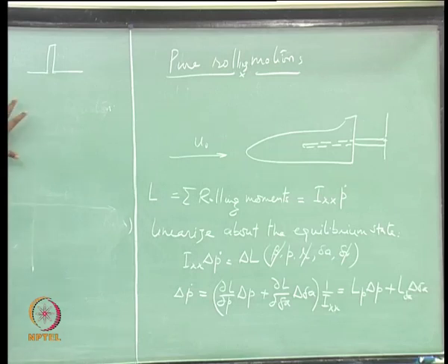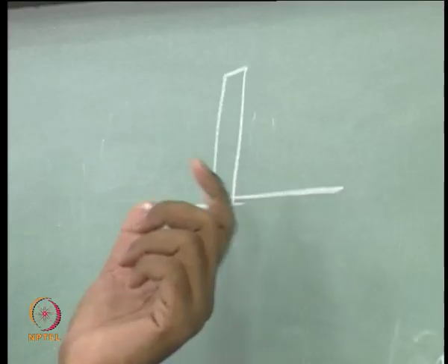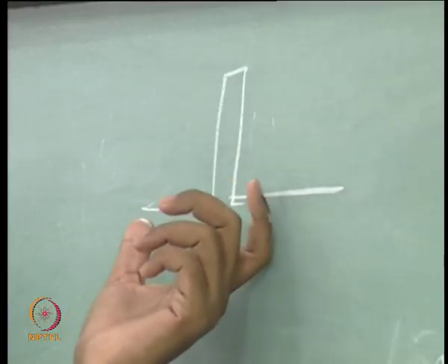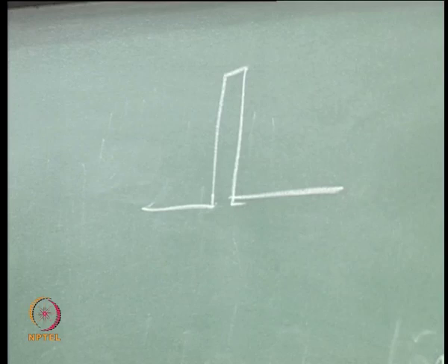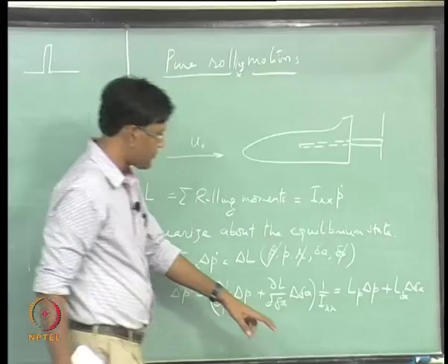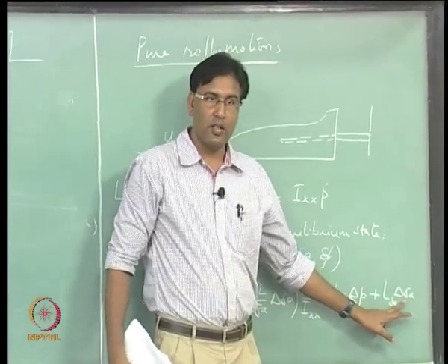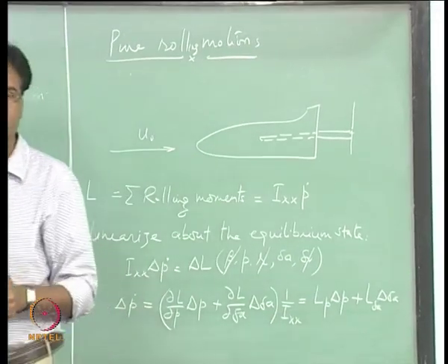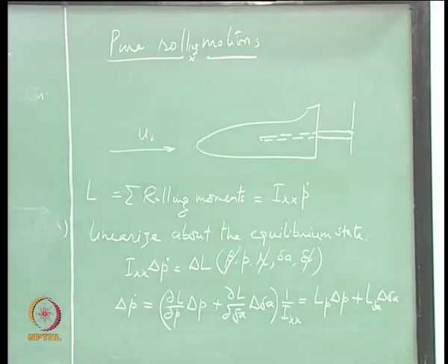Okay. So, there are two ways of doing this. One is to give a perturbation in the initial condition and simulate the aircraft linearized equations of motion. Second thing is you can give an impulse or pulse input, a pulse of very small duration, to the control input, right. So, it acts like a disturbance. Okay.